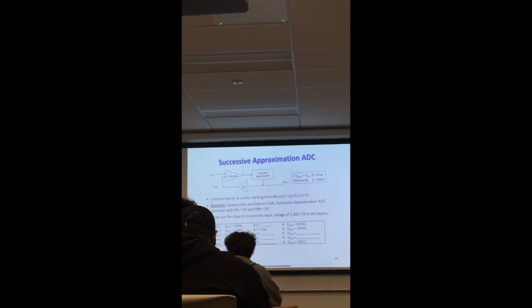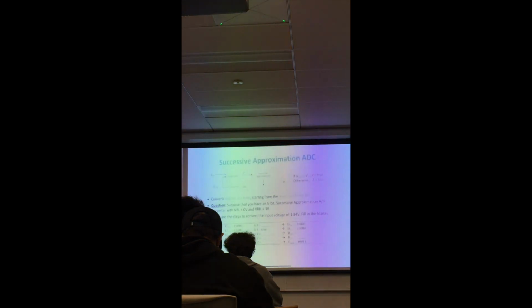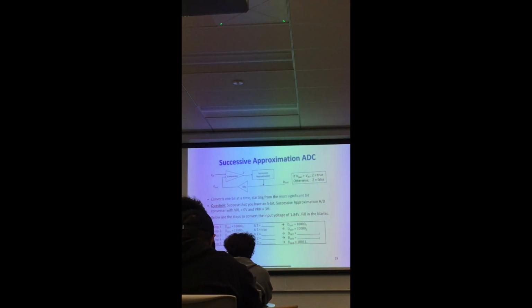Given the resolution, for example, you want to obtain a value in the range of 1 byte, which means 255 levels, right? The time that it will take to process the analog to digital conversion depends on the number of bits that you are processing, because the process is taking place bit by bit. And that timing is predictable.